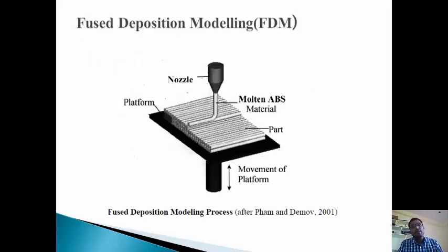The second example for the liquid base is fused deposition modeling. In this process, a movable nozzle moves along the XY direction on the substrate material. The build material is heated slightly above the melting point, so that it solidifies in a very short time. After extrusion onto the surface, the material forms exactly on the workpiece. The important factors considered here are the steady state nozzle and the material extrusion rate.